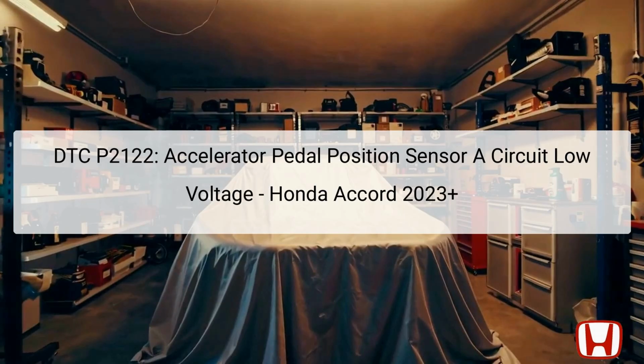The APP sensor is physically located integrated with the Accelerator Pedal Module inside the vehicle, where it plays a crucial role in providing real-time data regarding the driver's accelerator input to the engine management system. This information allows for optimal fuel delivery and engine performance. If the sensor's voltage output dips below the threshold of 0.2 volts, it will trigger this trouble code.